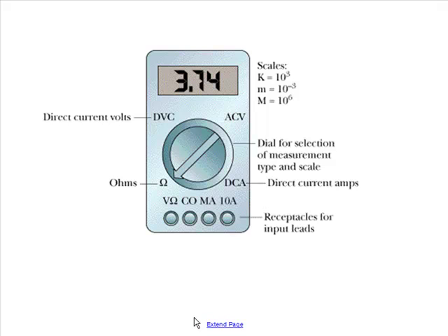It's a digital multimeter. Multimeter means it can measure many different things. This one's set to measure ohms. You'll plug wires into these receptacles here at the bottom. You will always have a wire in the common. By tradition it's black, but there's no reason it needs to be. Your other wire is traditionally red, but doesn't need to be, and it'll plug in here if you're going to use it to measure voltage or resistance, which we'll talk about in a minute. You'll plug it in one of these if you're going to use it to measure current. Generally start with it in this 10 amp side.